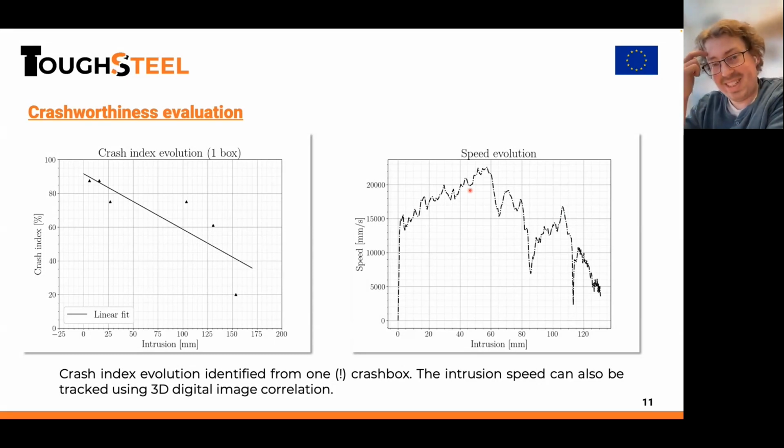It is, however, hard to separate crack initiations in the bulk material and spot weld fractures completely, because of course this is a very complex deformation. And an unbuttoned spot weld early in the experiment, for example, drastically changes the boundary conditions, which might provoke more severe cracking during input deformation, which could be seen from many crash boxes we tested.